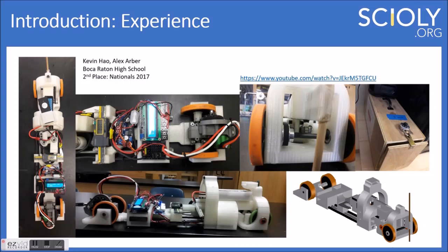Another thing that you can't really see in the device, well, you can see this threaded rod running through here. It's between these two carbon fiber rods. So this threaded rod is kind of how we initially adjusted our chassis. It's very important to have a very straight chassis. And we used that threaded rod to make sure that each side was even with each other when we were constructing it, because those carbon rods were very hard to adjust.